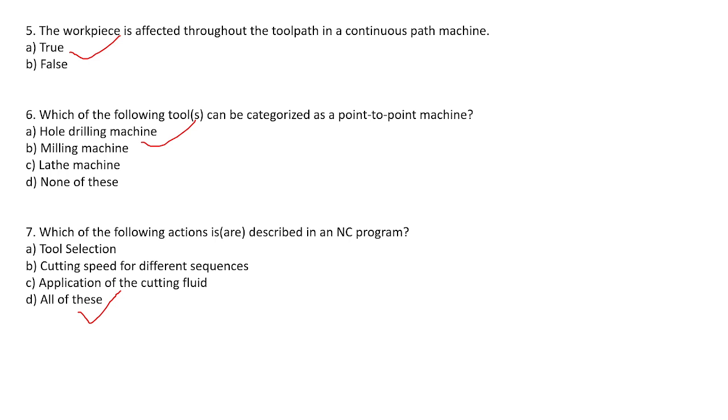G code, right? Yes, because we have seen that G code is used to control the movement and functions of the machine. So data is sent from a computer to the machine control unit through a communication device. We can use communication devices such as a parallel interface, USB, serial, or Ethernet connections.